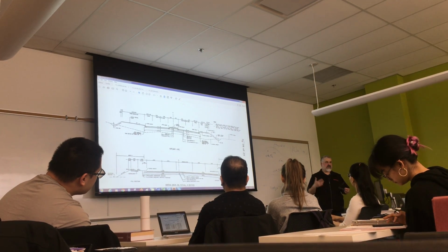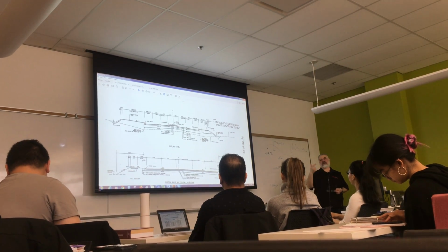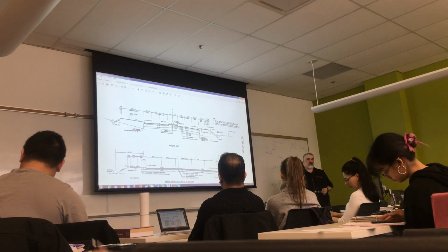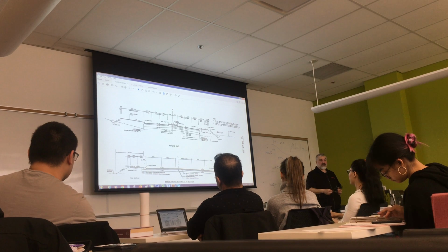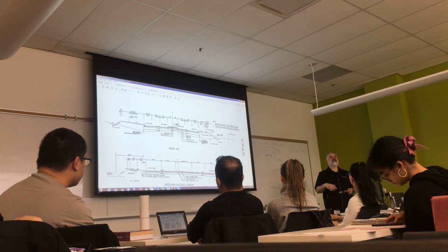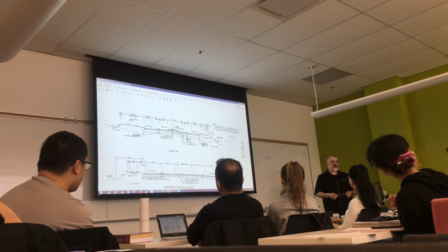For homework, you're going to get something very similar: a list of criteria. I'm going to tell you the road classification, the number of lanes. Is it tangent or super elevated? The pavement structure. I'm going to give you the design for the center of the pavement. I'm going to give you the existing ground cross-section data and so on. So you have to draw it. Draw it in AutoCAD, plot it to PDF, upload the PDF. That's the last question on the next assignment.